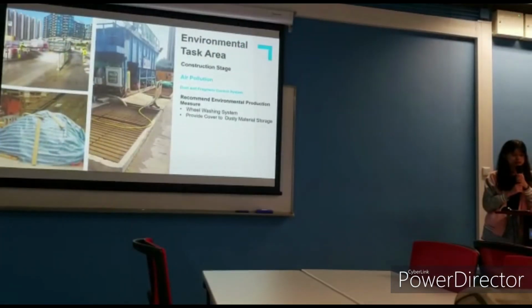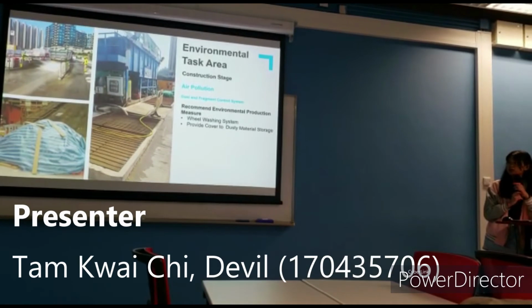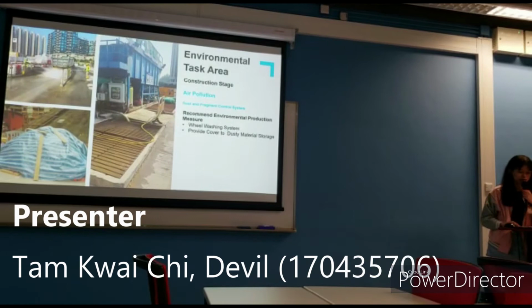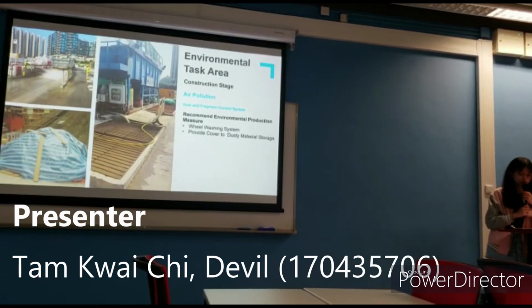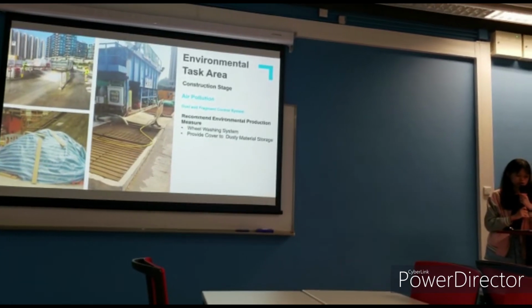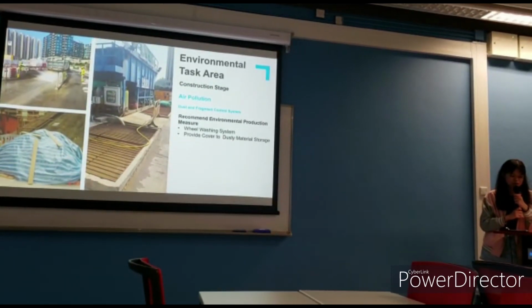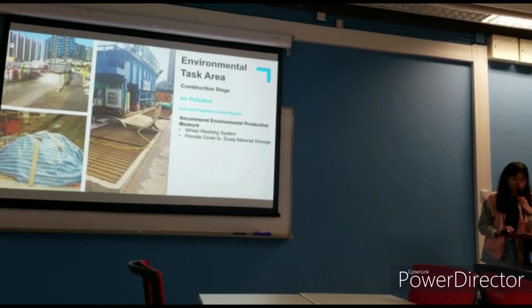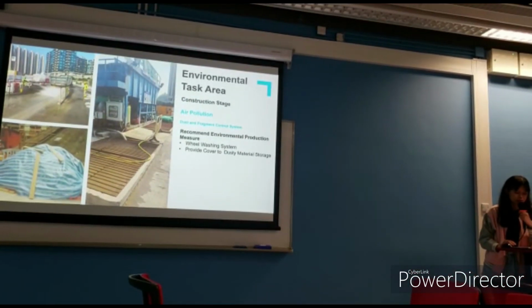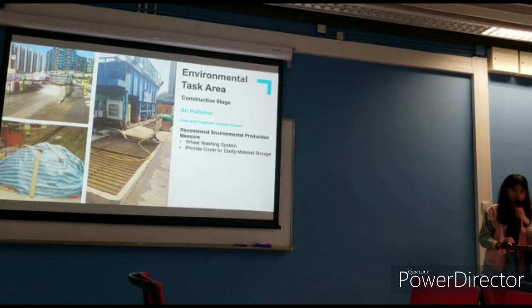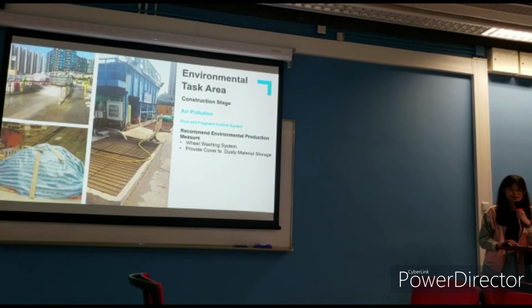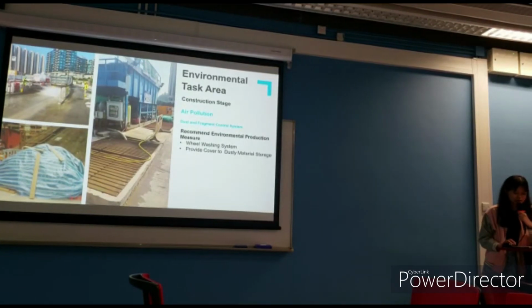Next, I will talk about the environmental aspect. During the construction days, it is very significant that air pollution and noise pollution will be caused to the public. According to the initial design of this development, the proposed ground level will be higher than the existing ground level. So the soil will be excavated from the ground and will need to be filled and compacted for the site formation work in the future. There will be no more room on the site for soil storage during the construction, and therefore all excavated soil will be transported to another place to be stored.